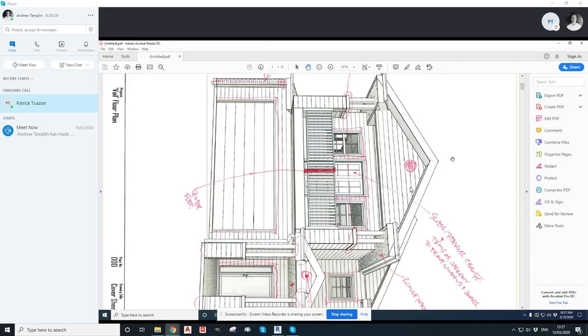And the column would be set at a certain height, so it would look like a post. Does that make sense? Yeah. No, you wouldn't use a wall. Sorry, you would actually use a column. So typically posts are 100 timber posts or 90. So they're the two options.